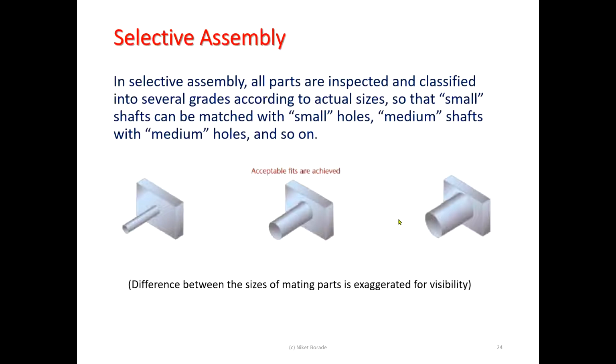You make some near the larger maximum limit shafts in one place, near the minimum limit shafts in another place, and in between in another place. I'm just making 3 groups for ease. Maybe you can make more groups, but you can see what will be the effect.